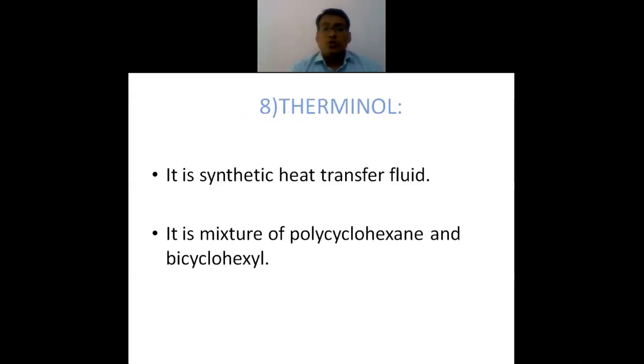Then Therminol, that is another thermic fluid which is commonly used in industries. Therminol is a synthetic heat transfer fluid. It is a mixture of polycyclohexane and bicyclohexyl.